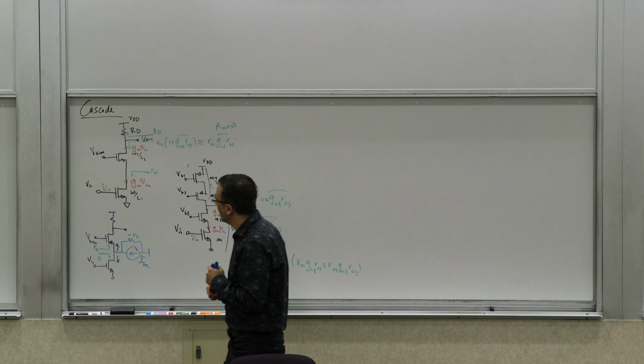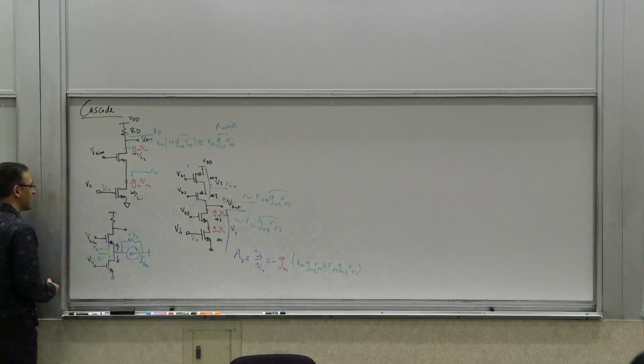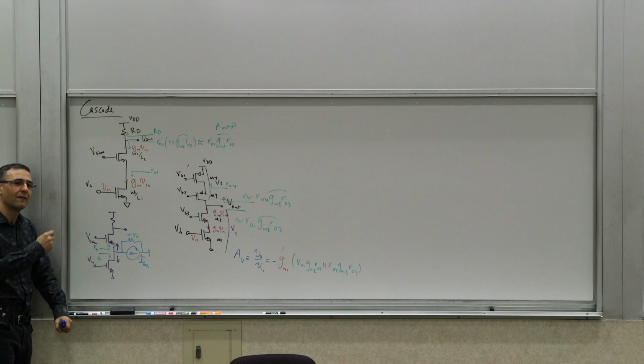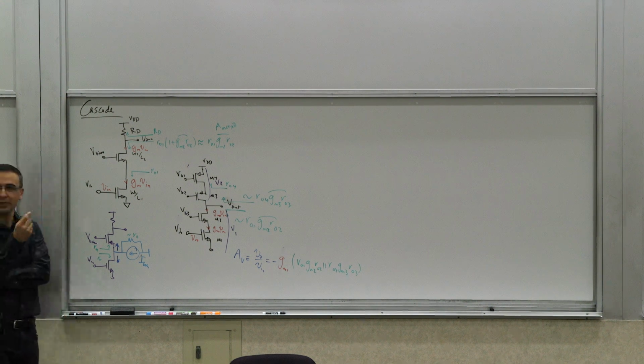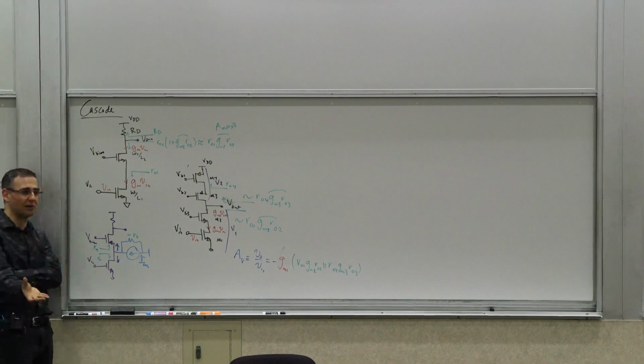So she says, I said the resistance looking up here is RM, but does it matter which way the current is flowing? Well, remember, this is important to recognize. That small signal model is valid because it's a perturbation. It's valid for NMOS and PMOS. Actually, it's the same for an NMOS and PMOS. It looks the same because it's a perturbation model. It's a derivative.